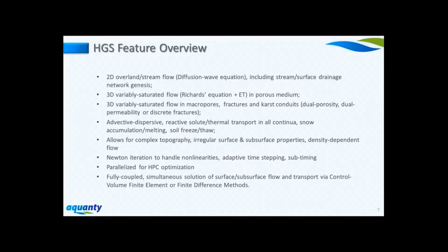In some of these cases, we, for example, have been working with HydroGeoSphere for simulating performance of deep geologic repositories for high-level radioactive waste storage. You can take several approaches: a dual porosity, dual permeability approach to handle these features, or, if needed, discrete fractures and faults. As I mentioned, for solute transport in both the surface and subsurface regimes, we solve the advection dispersion equations.